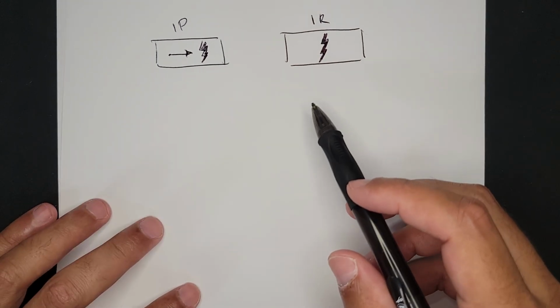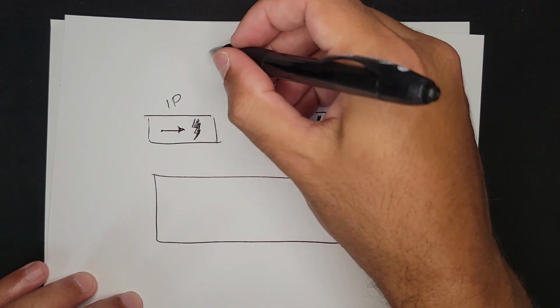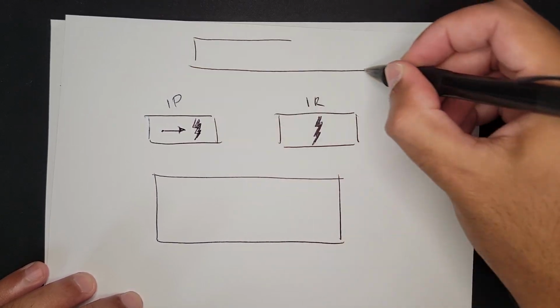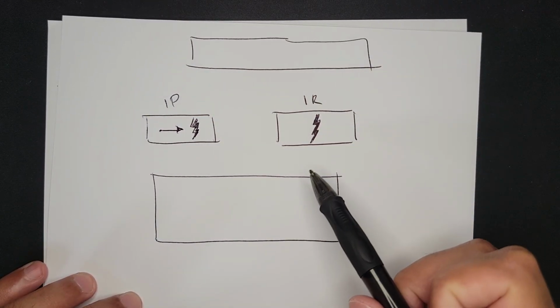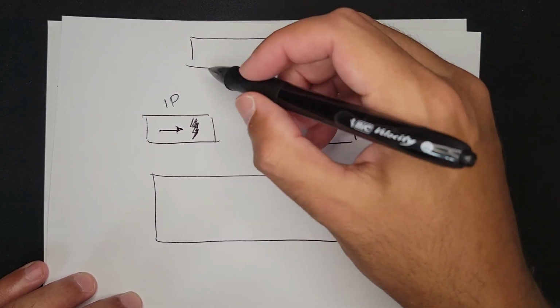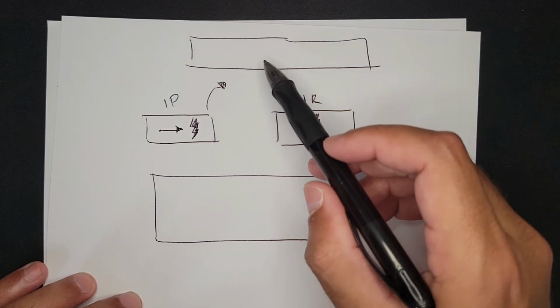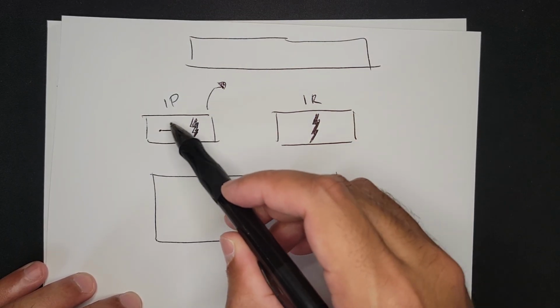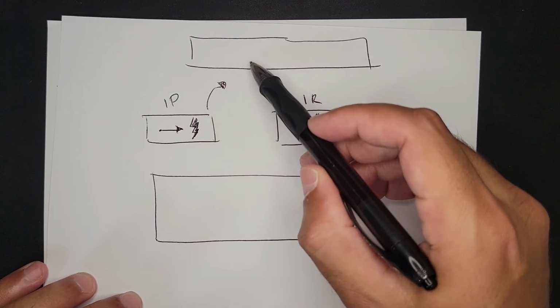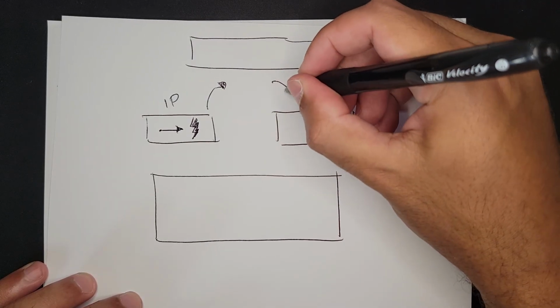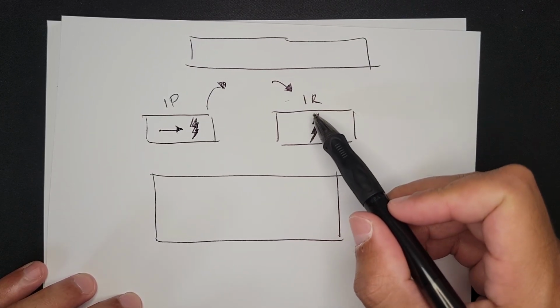So we have our control system here. And then we also have our RAM. And let's say the RAM is right here for convenience. So let's say this is our RAM. What needs to happen for every CPU instruction that's being executed is we need to send the instruction pointer to the memory controller, who will look up this address. So we're going to look up this address in memory, and then we're going to output the data, the instruction itself, into the instruction register.